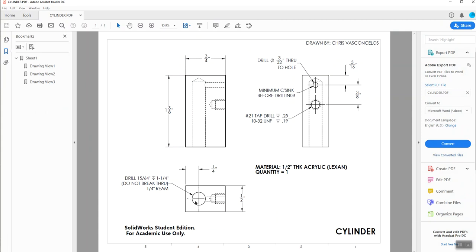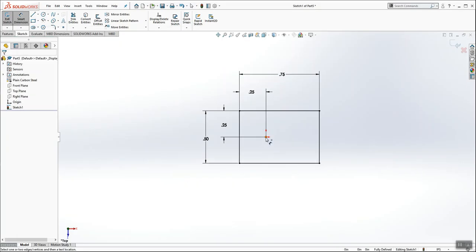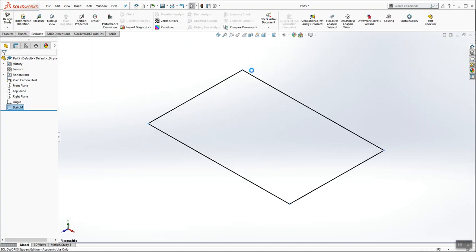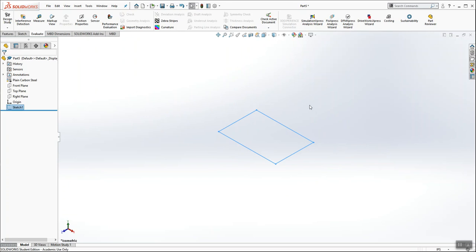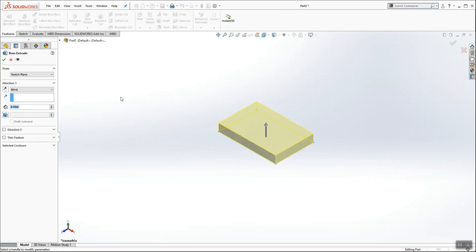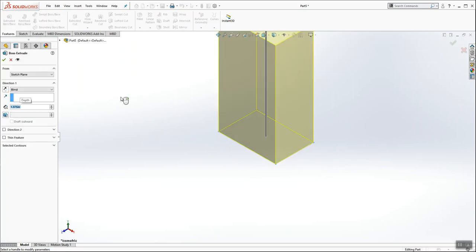This hole, this 1/4 inch reamed hole, is for the piston. So by putting it 1/4 by 1/4, I'm putting exactly where it needs to be. And if we look at SolidWorks, this origin is going to be the location of my Hole Wizard hole, which we'll take care of in the next step. So with this modeled on the top plane, and you'll notice I like to revert back to my isometric view. There is my rectangle on the bottom. There's the origin. I'm going to extrude it upward to the height of the cylinder, which is 1 3/8.